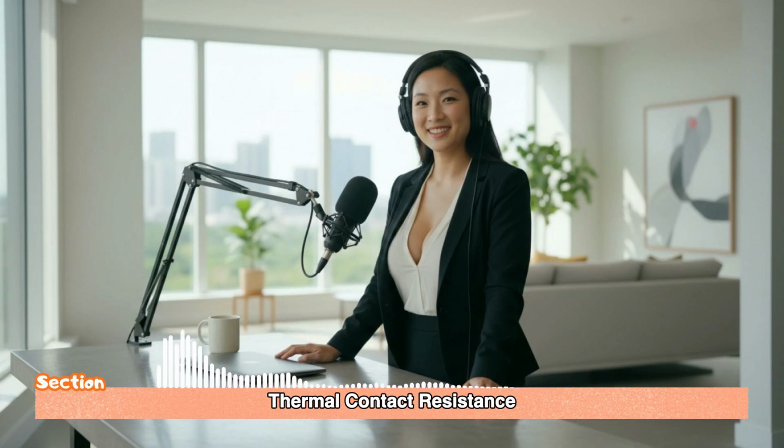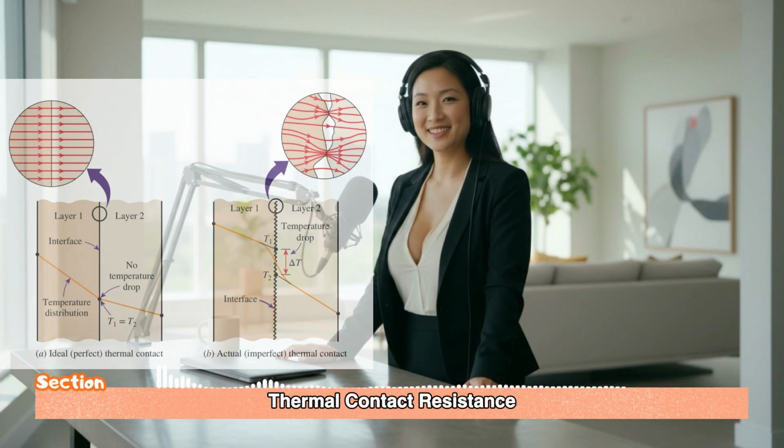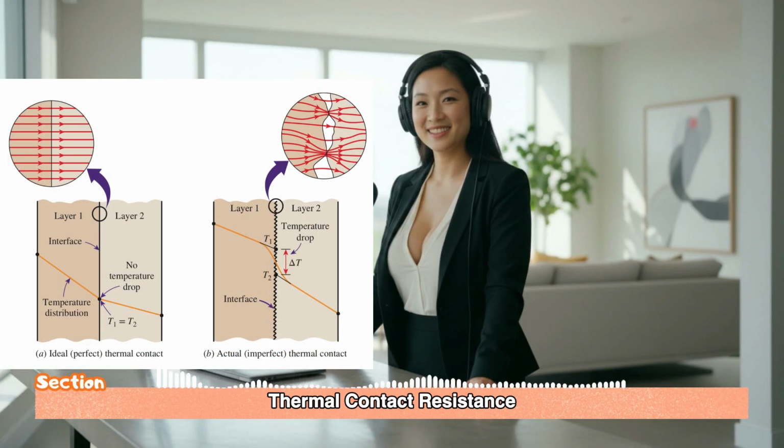We built our whole network theory on this idea of perfect contact between layers. We assume the temperature at the boundary of one layer is the same as the temperature at the start of the next one. No drop. But microscopically, perfect contact is a myth. It just doesn't exist. No matter how finely you machine a surface, it's rough. It has peaks and valleys. When you press 2 solids together, only a tiny fraction of the total area, maybe less than 2%, actually touches. And the rest of the area, the vast majority, is these microscopic voids, gaps that are filled with air.